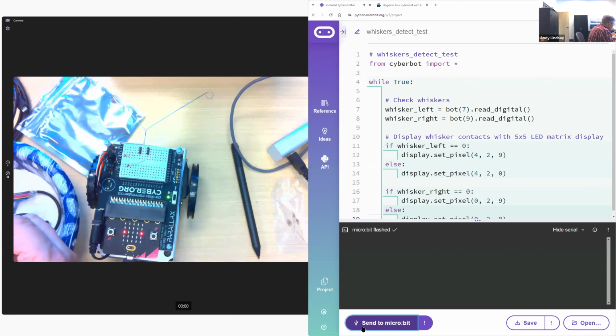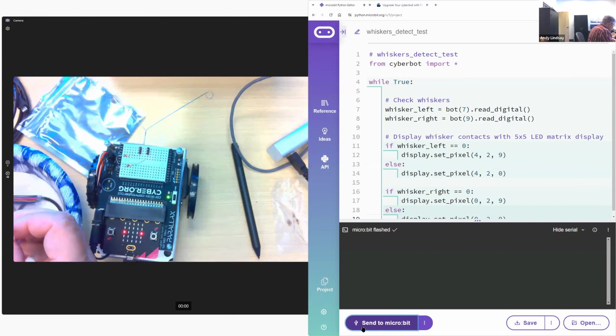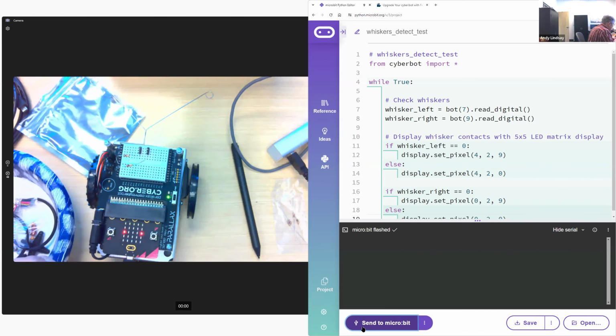Yeah, and be careful also, because you want to have red, red, brown, not red, red, red for your resistors that are connecting to the I/O pins.